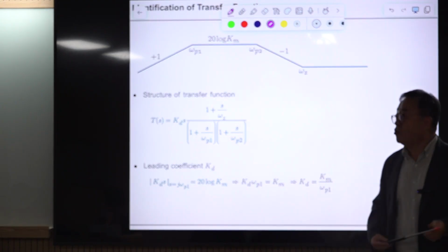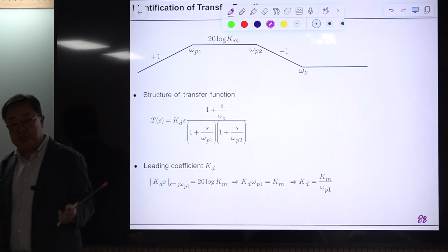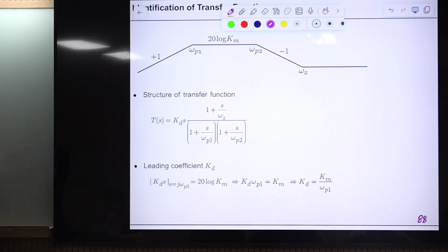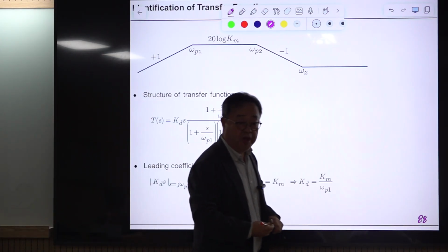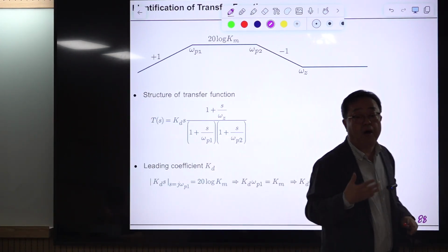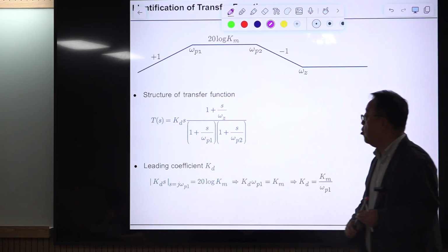During manipulation of transfer functions, you will be using the asymptotic plot of each transfer function, and you add them together, divide them, and multiply them. Everything can be done with this asymptotic plot, graphically, without any calculation or any algebraic manipulation. That is the more useful, more high-level application of this Bode plot.